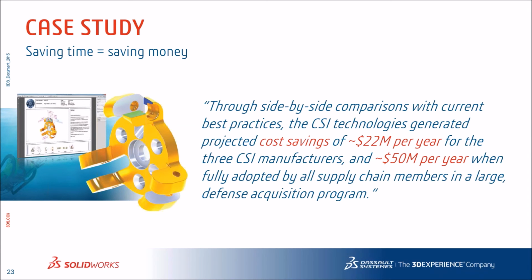So that wraps up the workflow that's required for creating an MBD document. Again, DimXpert is something that you have today, and there's nothing stopping you from adopting it right now and using it still to create 2D drawings, and then eventually when you adopt MBD, you can go ahead and create the 3D manufacturing documentation. But then we can organize with MBD and export it either to an eDrawings file or a 3D PDF that anyone can open.